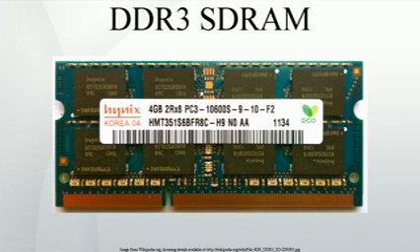Sometimes, a vendor may misleadingly advertise the I/O clock rate by labeling the MT/s as megahertz. The MT/s is normally twice that of megahertz by double sampling, one on the rising clock edge, and the other on the falling. In comparison, DDR2's current range of data transfer rates is 400 to 1066 MT/s using a 200 to 533 MHz I/O clock, and DDR's range is 200 to 400 MT/s based on a 100 to 200 MHz I/O clock.